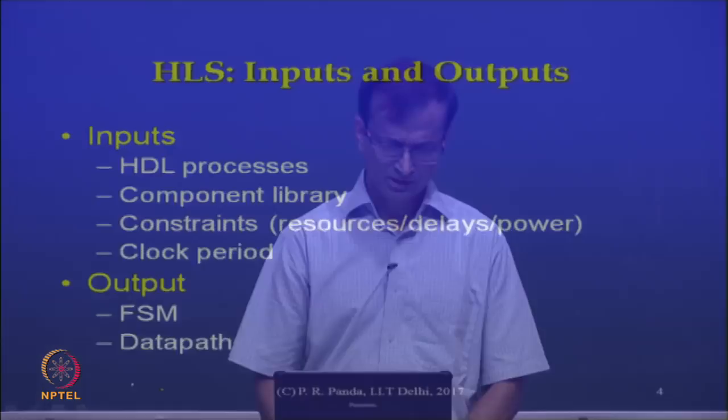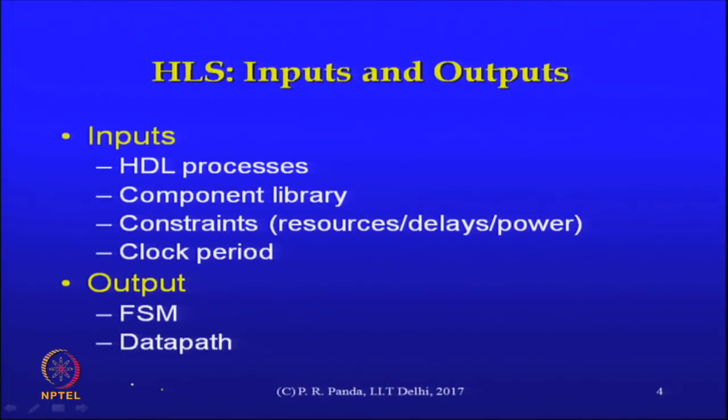Clock period is typically also imposed as a constraint, although you could have a variation of the synthesis process in which you can ask the synthesis tool to come up with a solution, and along with the circuit it also gives a suitable clock period for the design. It could be, but usually the clock period is provided as an input. And what are the outputs?